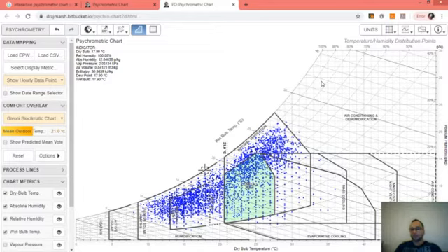It depends as well on whether there is cooking, different aspects that can affect the relative humidity indoors. So between 80 and 70, and with thermostat temperature set at 21 degrees Celsius. So 21 degrees Celsius dry bulb temperature, relative humidity 60%.